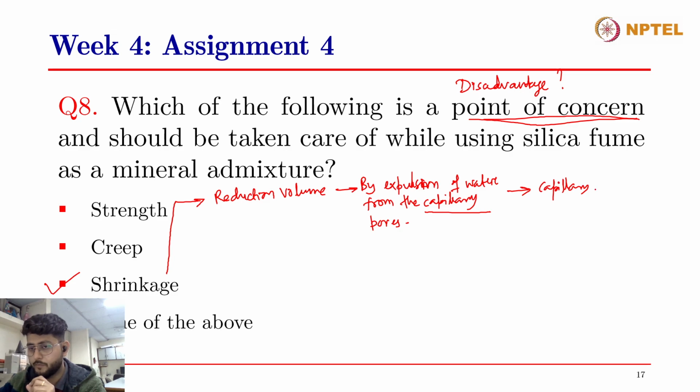When the water moves through these capillary pores, in or out, that increases the capillary tension. So when the water moves out, that creates capillary tension and that causes the shrinkage. If the shrinkage is restrained, meaning that if it is occurring in a hardened state or after the concrete has set, then this tension will cause cracks inside the concrete, right?